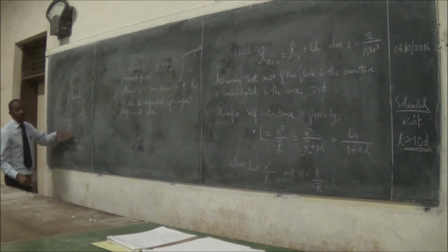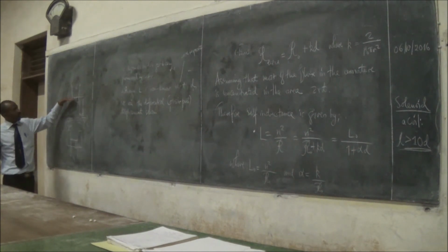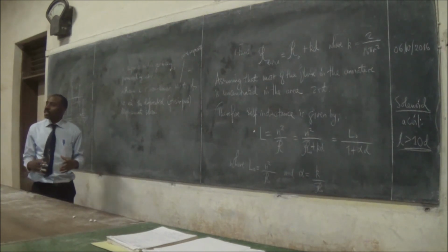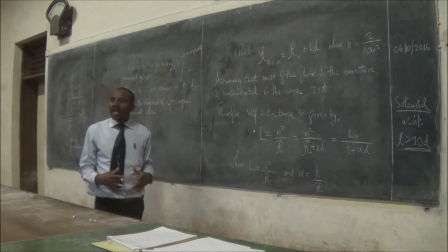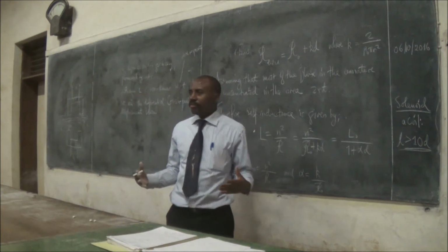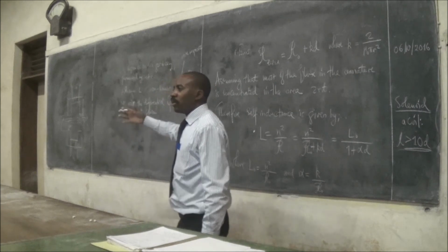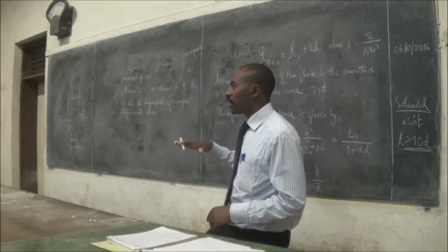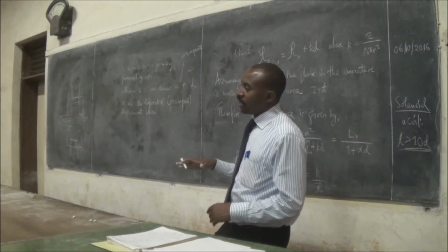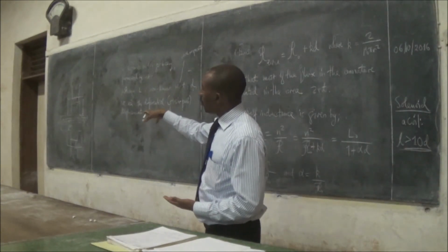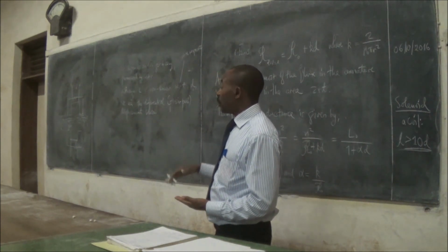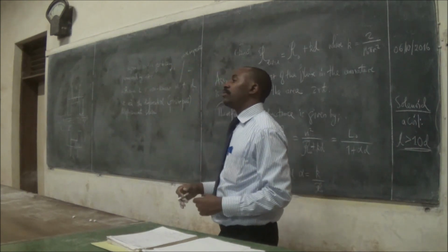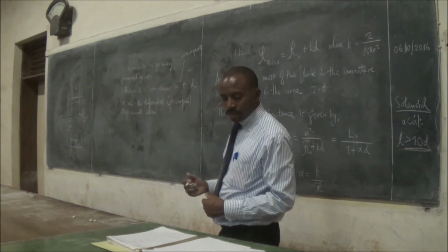X. And then we can work out the inductances L1 and L2, integrate them into our AC bridge, and get the V out in our bridge, and be able to get the value of how our sensor will be working. So if we have anything that is moving between the circuits, the armature AB, we will be able to get these two values, and then it will give us the reading. We shall do that on Wednesday.